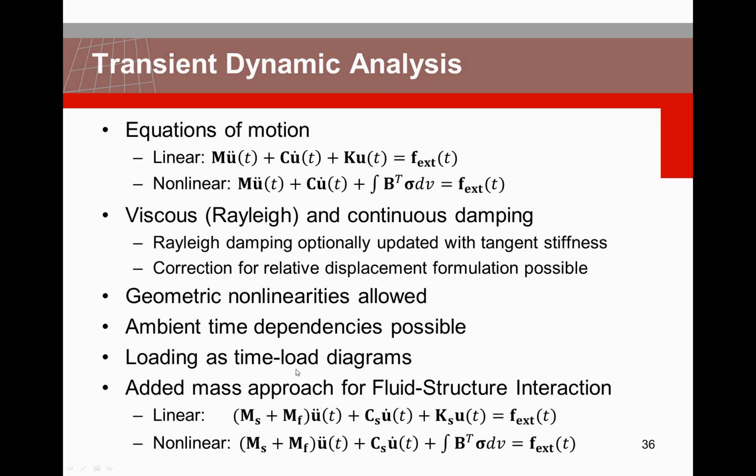The loading is provided as time load diagrams in combination with, for instance, base excitations or acceleration, but it's also possible just to apply this time load diagram to standard loads like forces, moments, or prescribed displacements. So you're not limited to accelerations. You can use all kinds of loading that you have available in the standard nonlinear static analysis as well. You can just attach a time load curve to that for most of the loads.